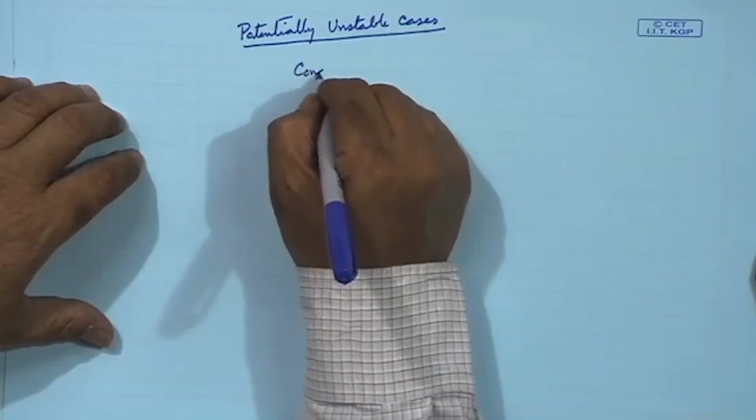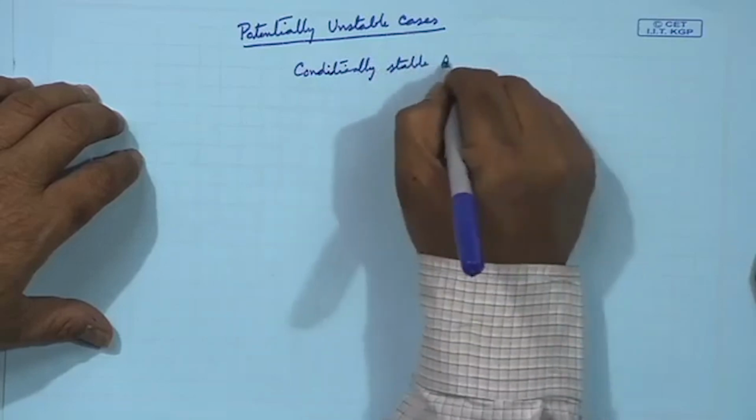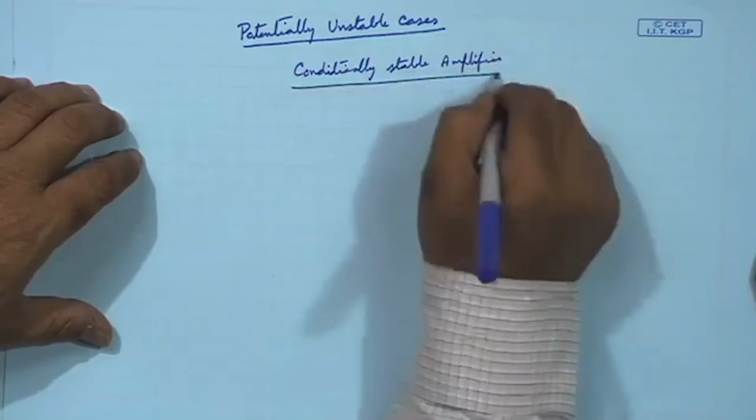to make a conditionally stable amplifier. We need to demarcate some zone of ZL, ZS, etc., so that we won't touch that, and we will also demarcate the zone from which we can choose ZL, ZS. Those are called stability circles, drawing them and determining the region where it can be conditionally stable. This is something like what you have learnt in control circuit classes, that when any network is becoming unstable, you can find how to make it conditionally stable. We will also see that in the next lecture.